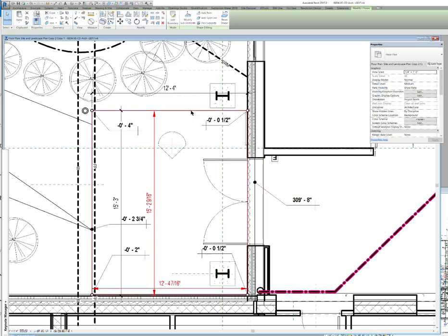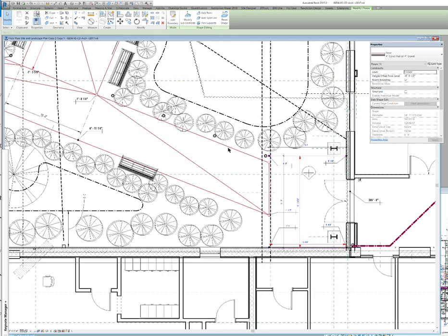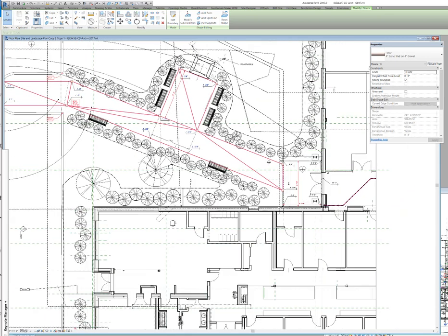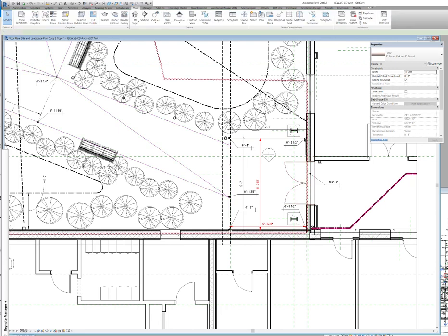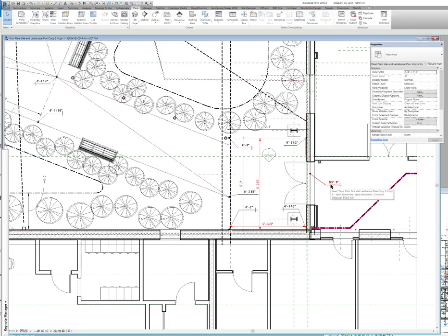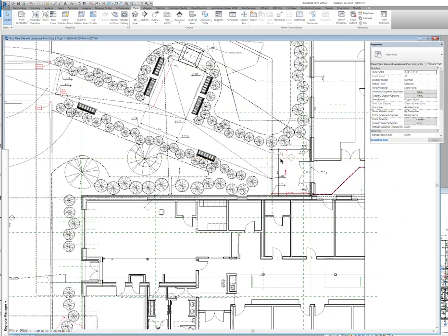Alright, so I've created a slab here and a slab here, and the properties that I'm trying to do, the design is supposed to be that this starts along this line at a ½ inch down from the first floor elevation, and it pitches 1/8 of an inch this way, and then from this point it pitches 1/8 of an inch that way. So you probably know 1/8 of an inch to the foot is, not surprisingly, 1 inch in 8 feet, and it's also 0.01 for slope.